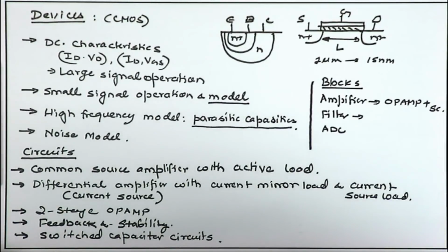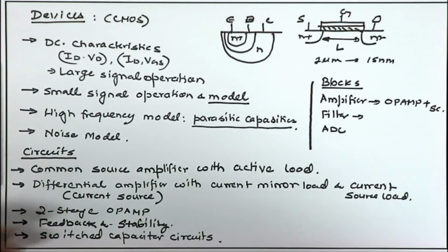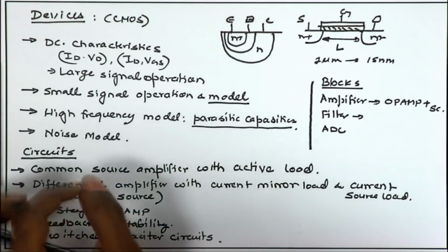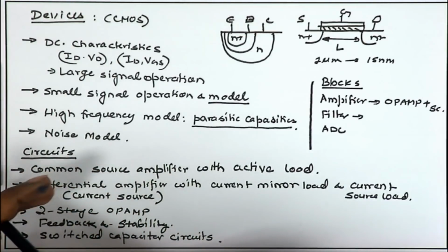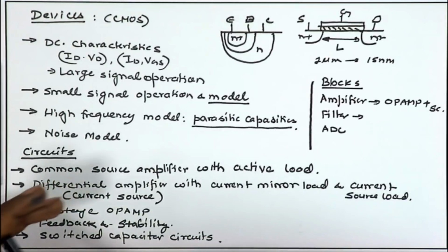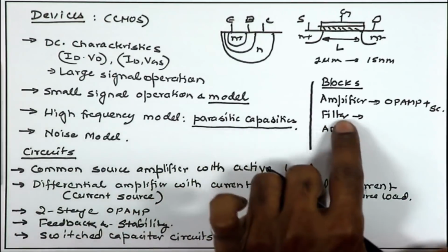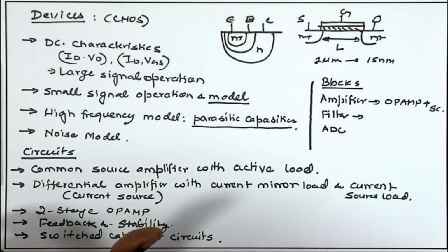Filters, once again, we are talking about not just some breadboard circuits where we have large resistances and capacitances at our disposal that we can use to get a desired frequency response. While designing filters for integrated circuits, we are faced with certain stringent constraints. You cannot have any arbitrary value of R and C. For example, on breadboard circuits and PCB design, we can have arbitrarily large C, millifarad, farad, microfarad, nanofarad. We have a very wide range of C and R through which we can design appropriate filters. But when we are talking about using on-chip components, the value of C and R that we can use to get the desired frequency characteristics is going to be very limited.